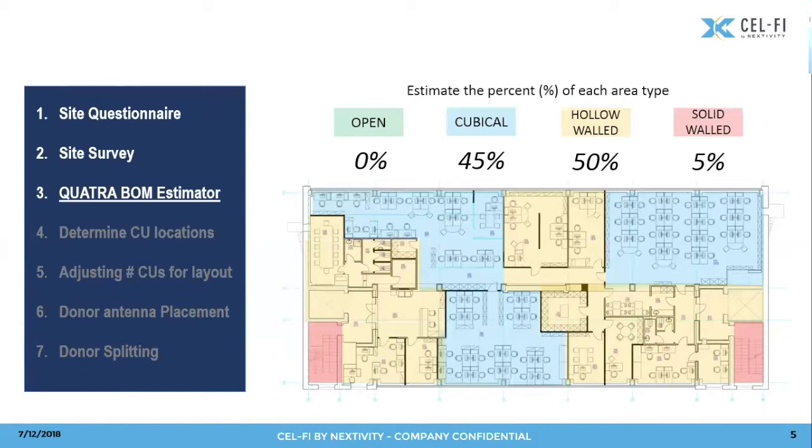And that gets further complicated because you're not even sure what the input power level, the donor signal level, is of these different operators for a passive DAS system, because it has to apply the same gain to each one of those channels within a band. Remember, Cel-Fi systems are different. We assign individual radio chains to every channel, which means we can apply more gain to a channel that comes in as a donor that is of lower power. We want to normalize everything to full power at our output. That makes planning simple. I know what my coverage is, or have an extremely good idea of what my coverage footprint is from every coverage unit.